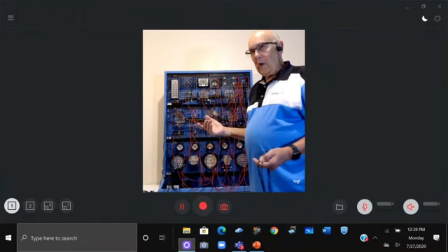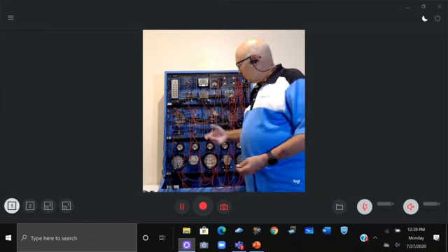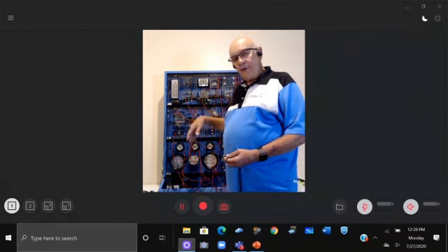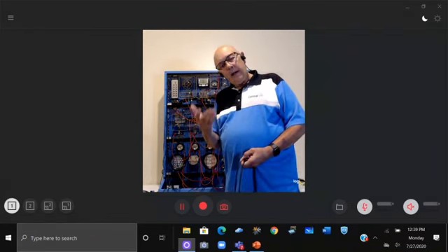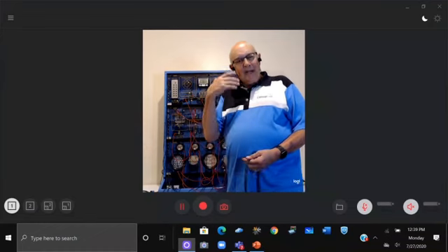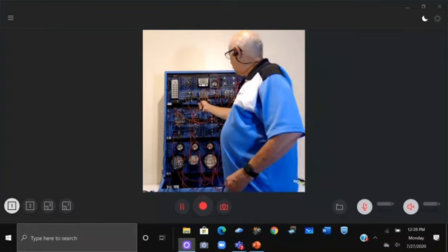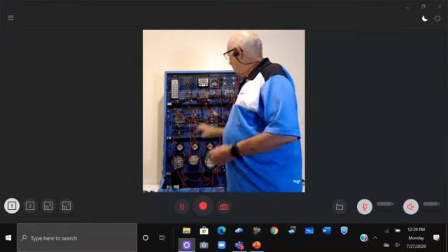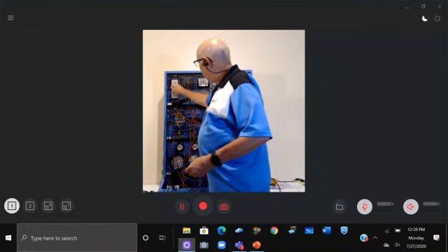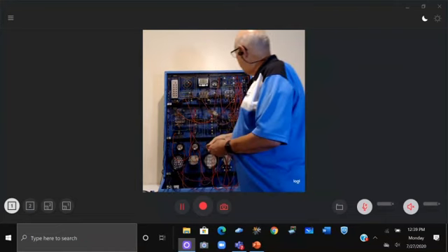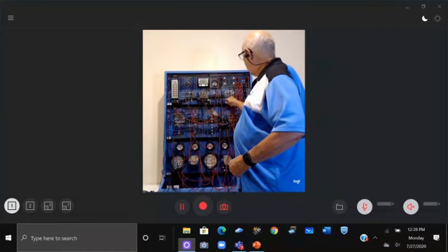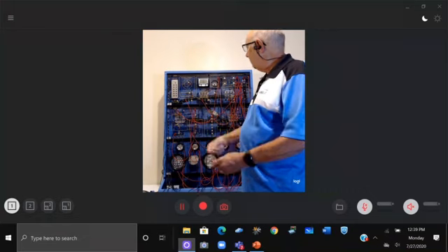If you teach it this way, teach so that every one of the modules has its own power and its own ground. That just makes a little more sense in the student's mind. Okay, the next thing we do is we run a ground. So we go back, here's the instrument cluster. We run a ground. Input module.